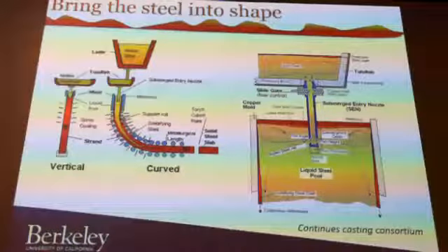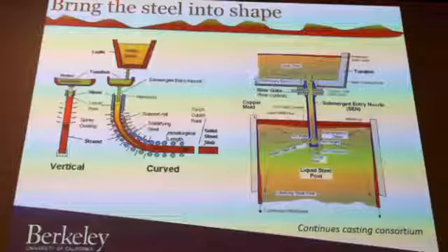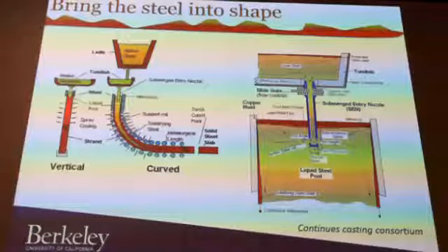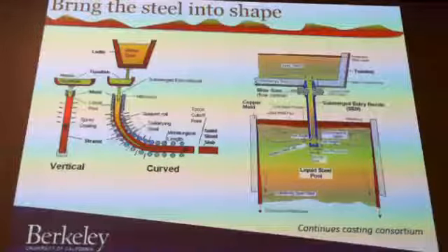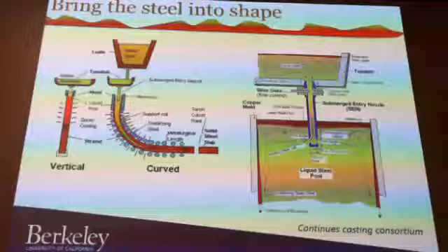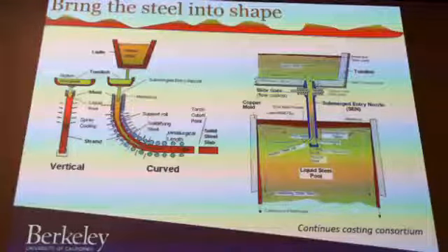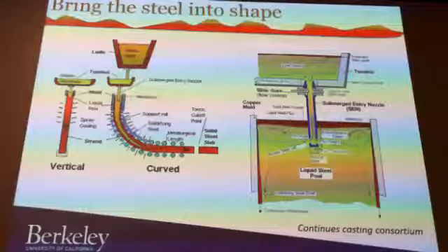So once you have your metal alloyed, now you have it liquid, which is great, but eventually you want to pour it into a state and a shape and a form you kind of want to use it. Now today there's a very nice process called continuous casting, where one pours in the molten steel here, and interesting is you pour it essentially in an open form, and it solidifies just on the outside skin and stays liquid in the center. And only as it is extruded further down, it solidifies on the inside. So the liquid core stays liquid for quite a while, and you can make endless products that way.